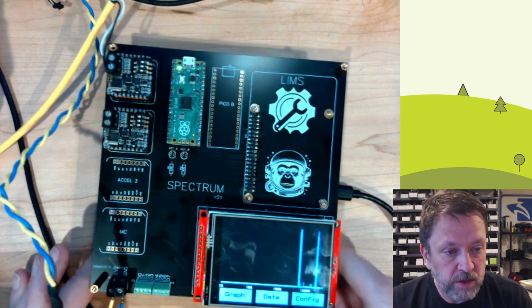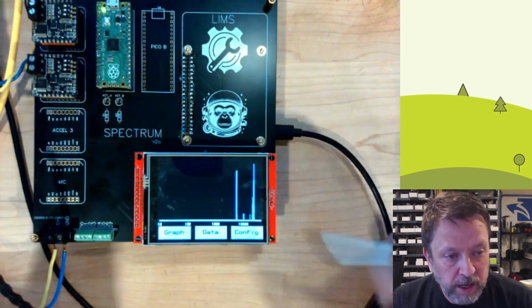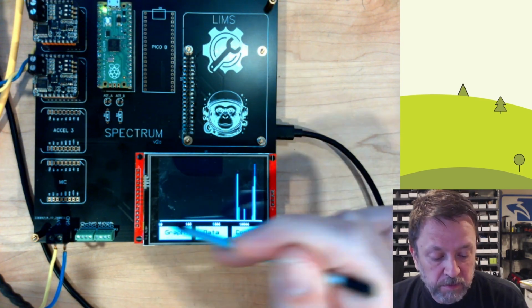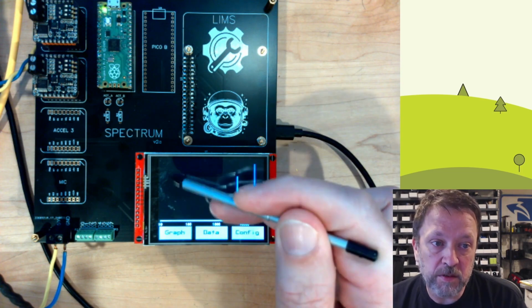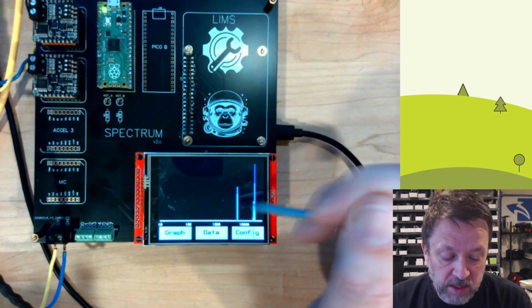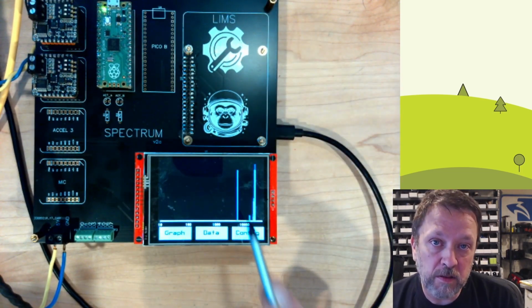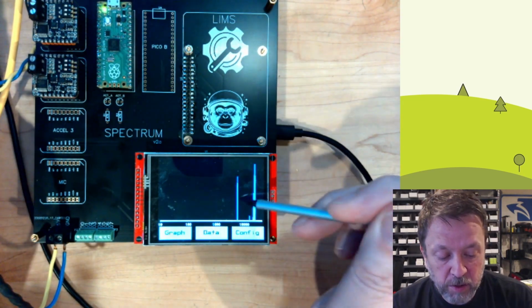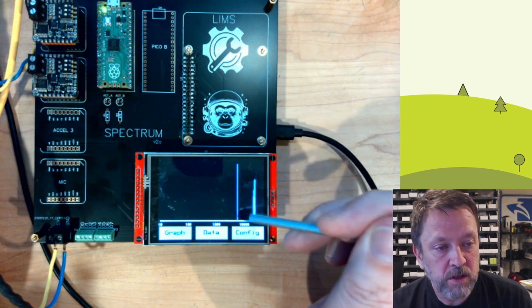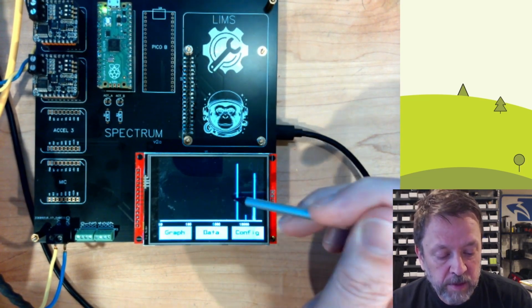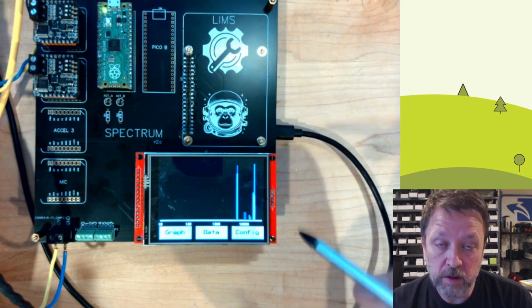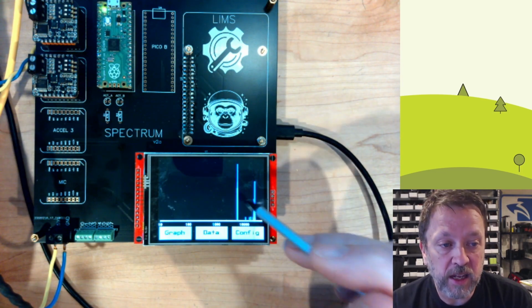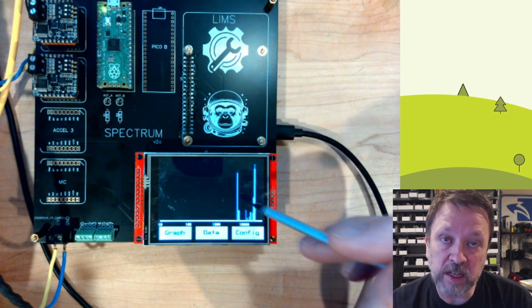You can see here, the graph view has 3 dimensions. Our X is a logarithmic frequency. Our Y is the magnitude of the signal. And so it's really just plotting those buckets that are the output from the FFT. And then the third dimension is the brightness of the color. So you can see there's some bright cyan and then darker blue. When signals come in, they're plotted in this cyan, and then as they age out, they fade to a darker color. So that's our third dimension.